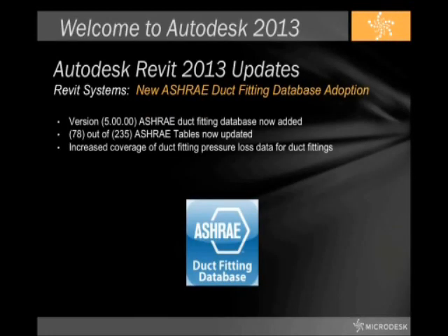As I was saying, what has been an add-on or add-in in the past, the ASHRAE duct fitting database, has now been adopted into Revit, so it's now an internal part of it. And it's really a building block process. The latest version, 5.00.00, of the ASHRAE duct fitting database has now been implemented. It's using 78 out of the 235 ASHRAE tables, and those have been updated.